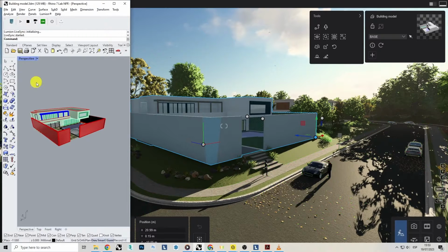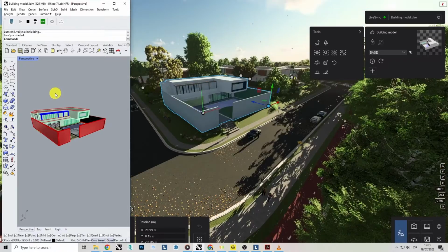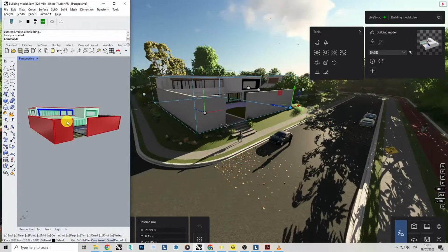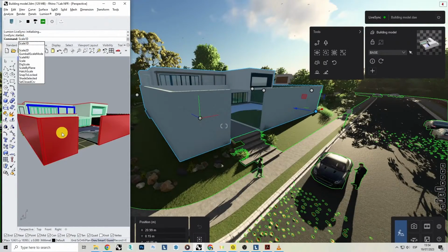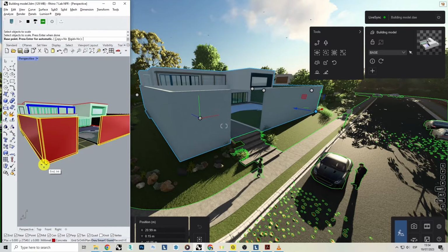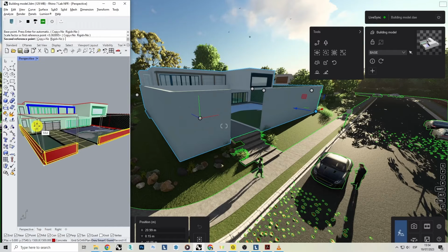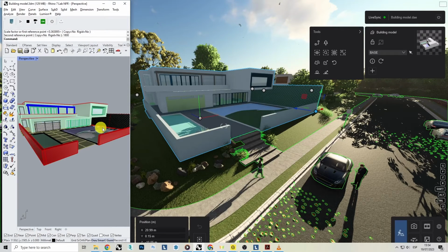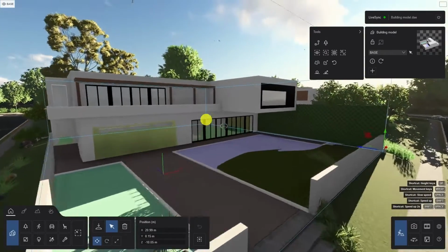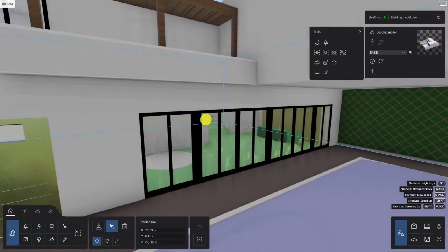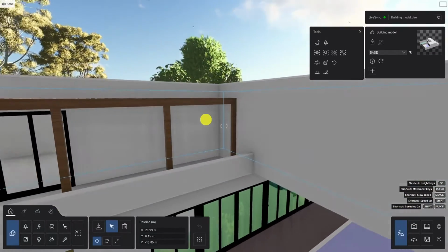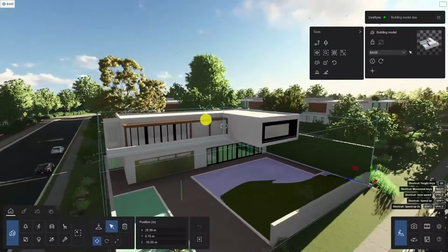This makes it much easier to stay present within your design workflow and limit the amount of back and forth you need to have between applications. Once a model is imported, you can modify the geometry, and a second later, Lumion will display the modifications. A nice and handy feature of Lumion is that the software recognizes the naming of the 10 most commonly used materials and will automatically assign them to your model. That helps us to save some time and get working on the details much quicker.